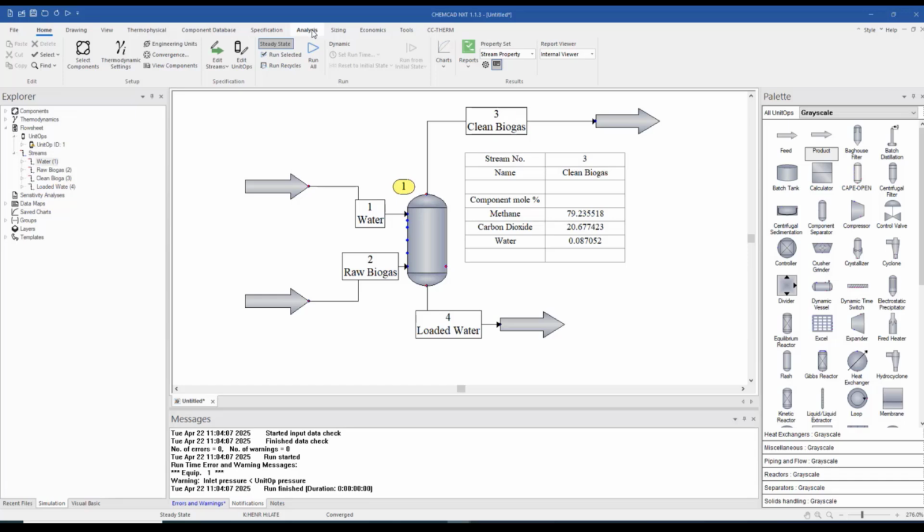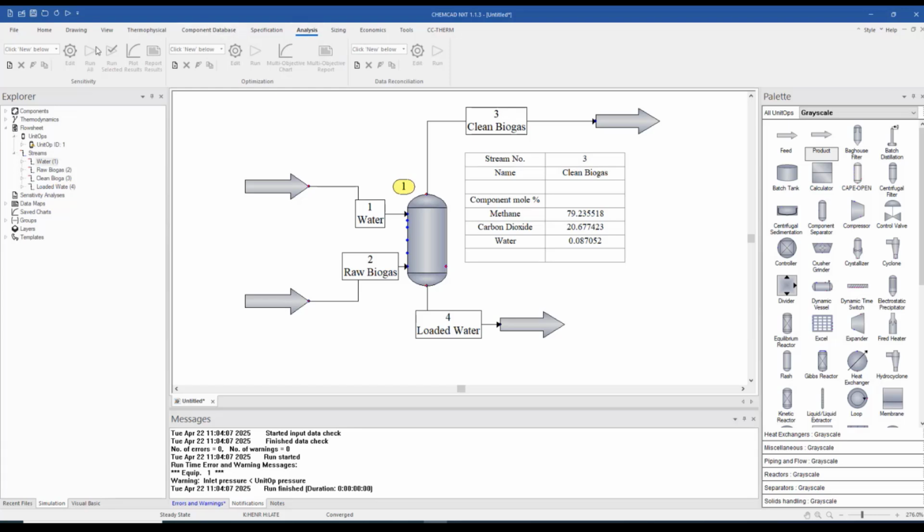parameters. So we go to the screen analysis, and here we have the sensitivity. We set up a first sensitivity study. So let's start with two parameters because it's easier to see the effect of two parameters. Three are quite hard to visualize. So we select temperature and pressure.